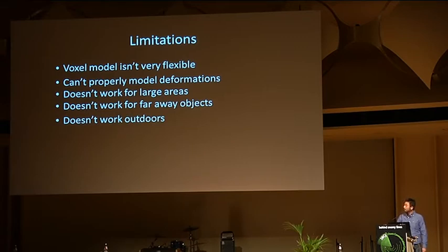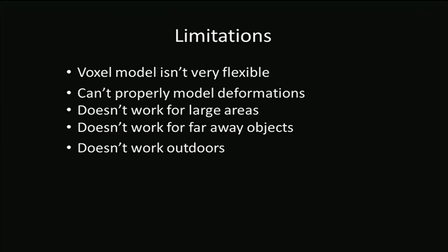And another limiting factor of Kinect is it doesn't work under sunlight. Kinect operates in the infrared wavelength spectrum, and because the sun also emits infrared, we can't create enough contrast in the sensor image to acquire the depth of surfaces.